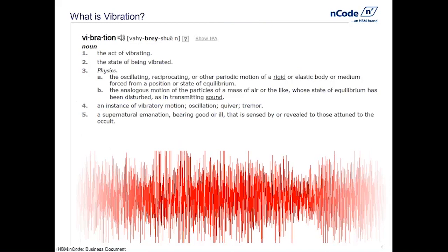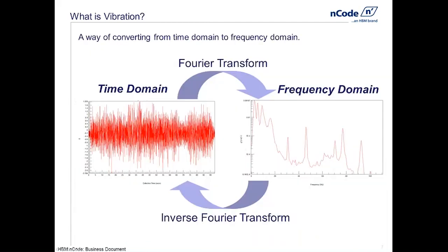Another way to think about this from an engineering perspective would be inertial loading. So vibration fatigue makes sense when we have parts that are inertially loaded. If we don't have that, we may have non-dynamic or quasi-static loads being applied, and those are not represented in the frequency domain nicely. So we have to keep in mind that vibration and inertial loading go hand in hand.